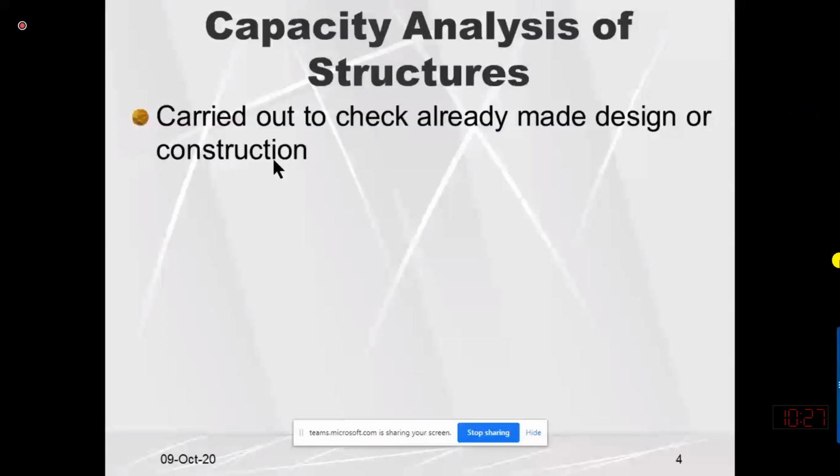So if we compute this moment, it is the moment carrying capacity of that beam. Then this moment value we will use to compare against the analysis. From the applied load, we know what load is considered, and from the applied load, we have plotted the shear force and bending moment diagram.